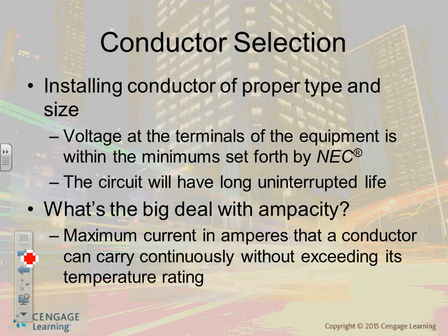It wasn't a 3-wire like that. Well, the AC does not need a neutral. Right, it doesn't have the ground. It was white, black and green. Oh, the green is the ground. That's okay. Yeah, you need two hots for the AC. But they made the white one red. Yes, that's okay. That's cool.